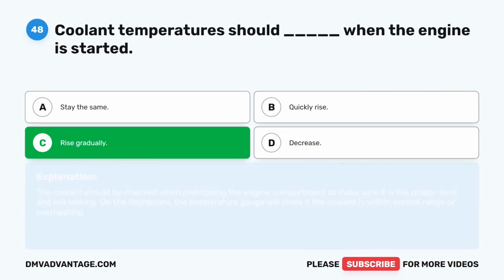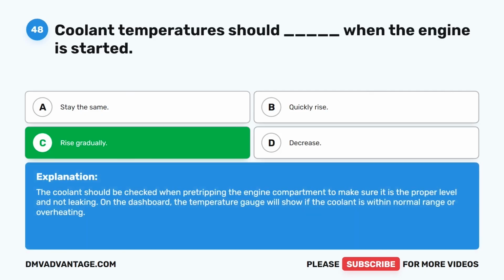Rise gradually. The coolant should be checked when pre-tripping the engine compartment to make sure it is the proper level and not leaking. On the dashboard, the temperature gauge will show if the coolant is within normal range or overheating.